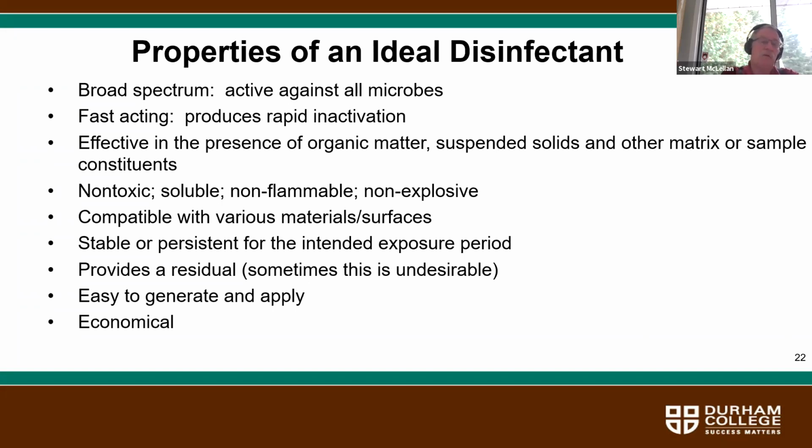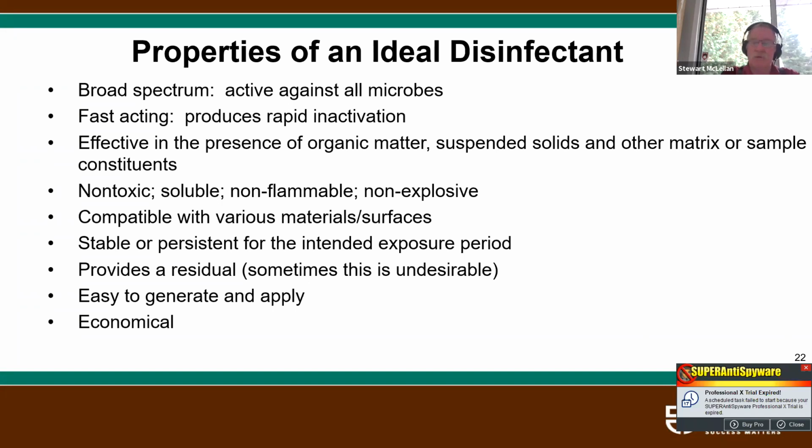When we're talking about potable water supply, disinfectants are added with a residual designed so that by the time the water reaches the furthest point of the distribution system, there will still be some remaining chlorine in the water to work against microbes.